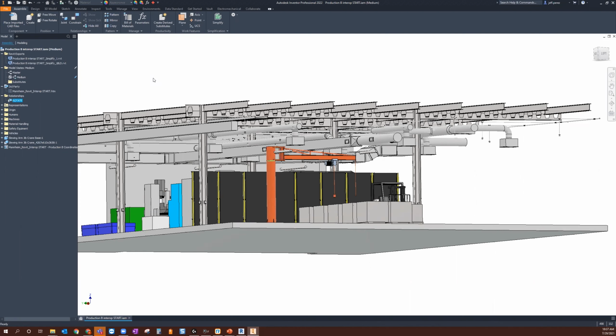Maybe you want to develop a library of these family files. It's going to take you, one, you're going to have to simplify the model, and two, you'll have to go through the BIM content environment to create an RFA export. Okay, so we'll do that now. I'm going to switch back into my master level of detail really quick. I keep wanting to say level of detail, but I'm going to switch back into my master model state.